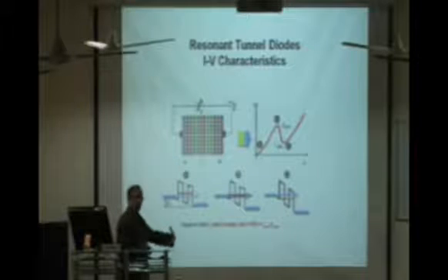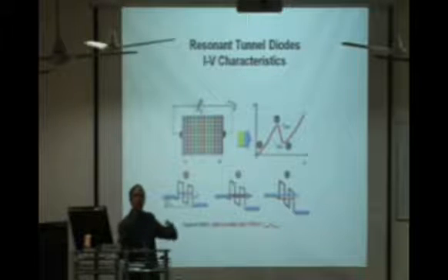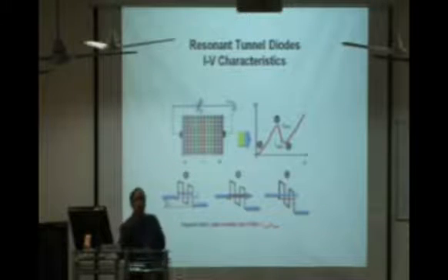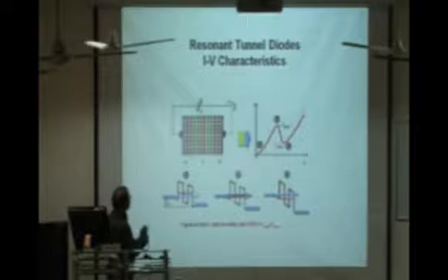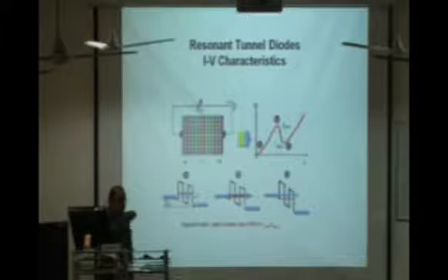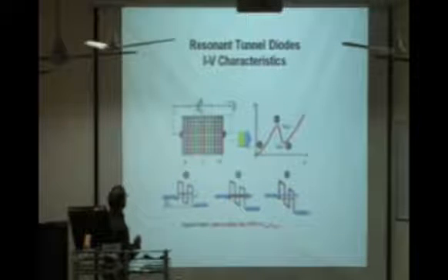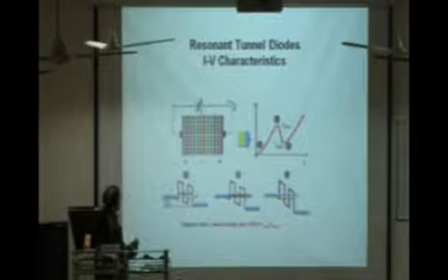As I said, one of the major candidates for making this solid state quantum computer, in addition to spintronic materials, is some kind of diodes called resonant tunneling diodes. Basically you can make transistors with a very, very small barrier between the two n-type regions. This is basically a double barrier structure. One barrier is here, one barrier is here, and this is the quantum well.